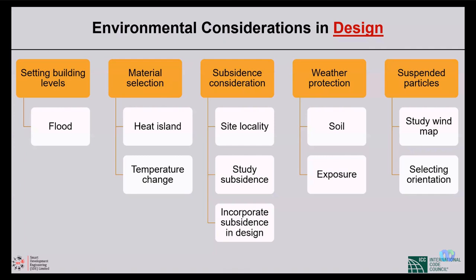This is site. We are talking about site locations, but we have to look at its surroundings. That is very important because you may not have a particular soil on that particular area that is good, but what happened to the surrounding? You have to look at that to understand clearly. And all these things you have to consider in the settlement calculations of your building in the design process, the subsidence.